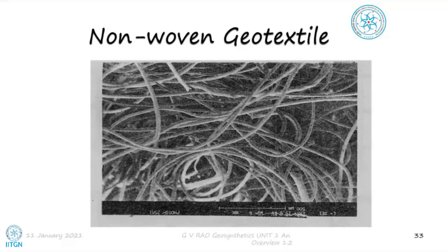So what has it got now? It has got openings of different size and different shape. That is most important for us now. Different size and different shape. That means this is what is going to make it like a filter material. Okay, what was it that our father Terzaghi decided as a filter material? He got different grades of soil particles, in order that he create openings which are going to allow water to get out and soil particles will be stopped from going further now.